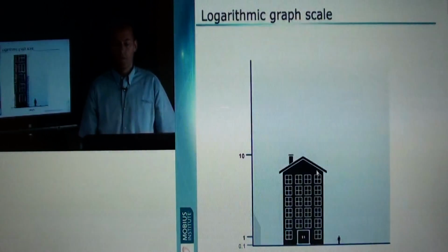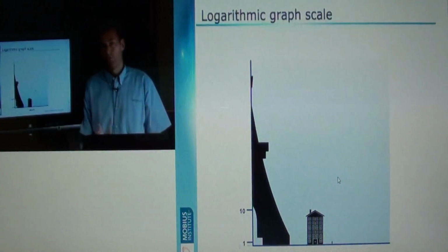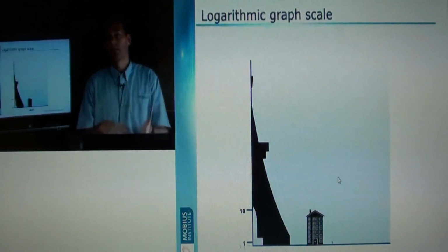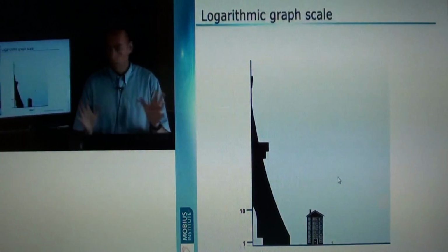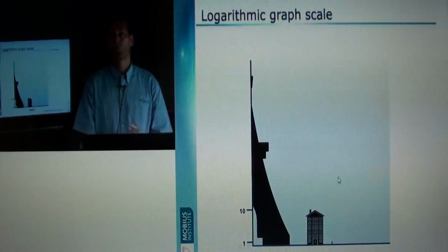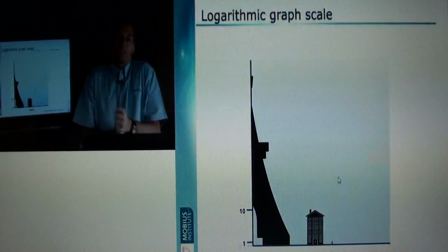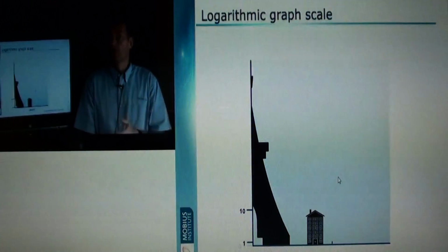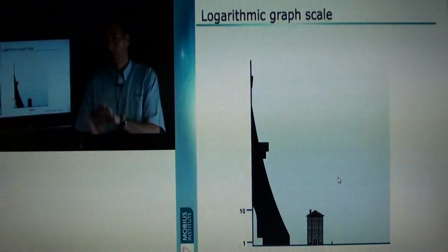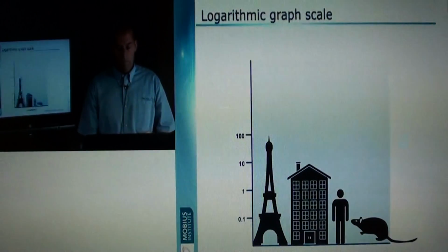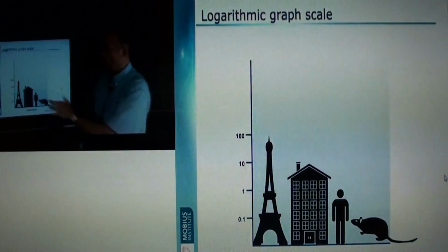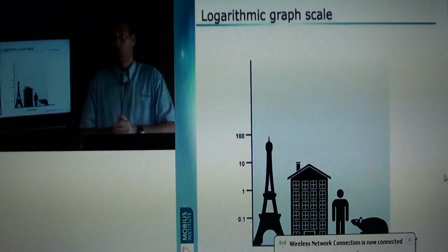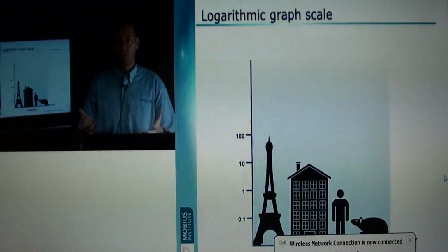But look, most software programs will have one button where you go doink and it toggles over to log and you can look at it and then go doink and toggle back. Now, I can tell you that there's a lot of vibration analysts out there, a lot, that just look at log. And it takes a bit of getting used to, because you see these peaks and you see a lot of harmonics, and you can think, whoa, look at all those harmonics, I've got looseness.